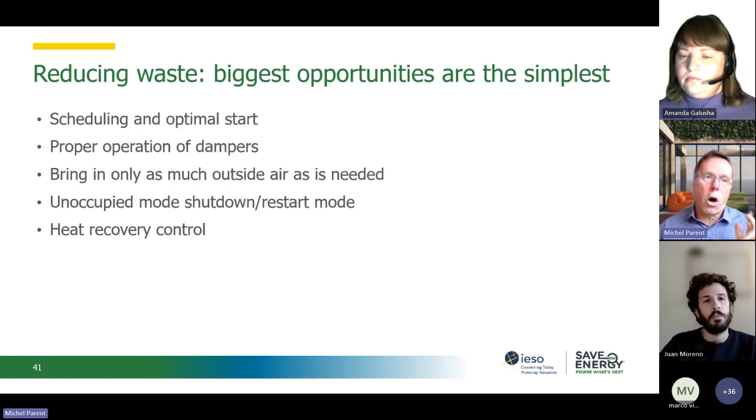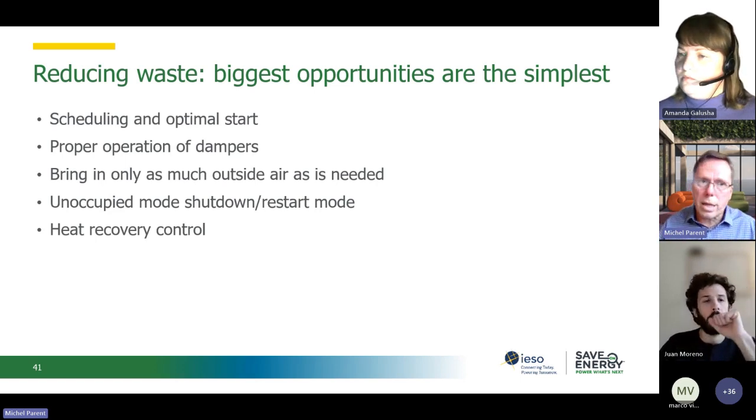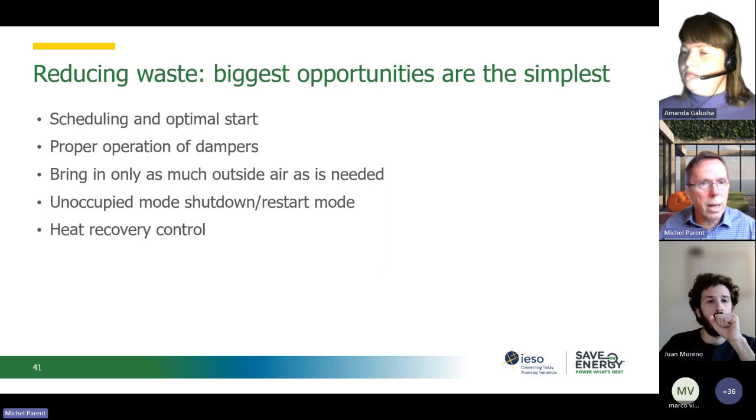So always keep in mind proper operation of dampers. And are they airtight? When I ask 10%, do I get 10% outside air, which is unlikely. So you can actually get savings out of that.